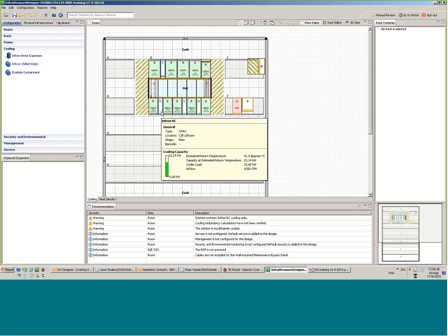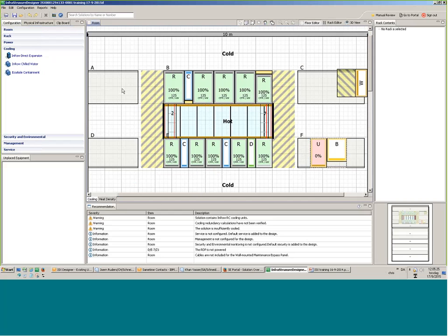manual of the ACRC 301H, don't forget that this is also limiting you, because in the manual this delta T is sometimes much higher. And if we see sales coming back to us and say, hey, but in the manual the cooling unit can do 50 kilowatt. Yes, can be, but the 50 kilowatt is not calculated with the delta T in the air of 14 degrees. And you know that our equal is not 100% airtight, so the 14 degrees is actually not the one which we have on the coil, it's the one on the server.